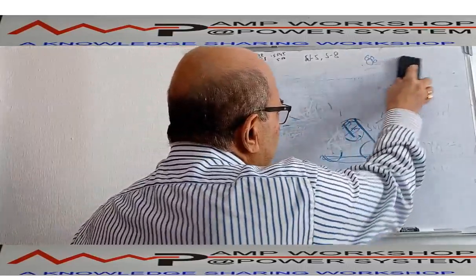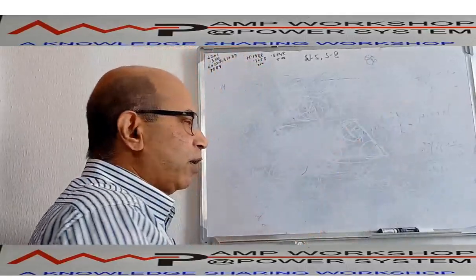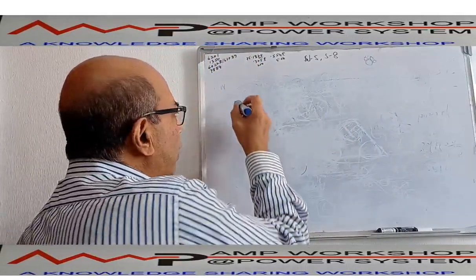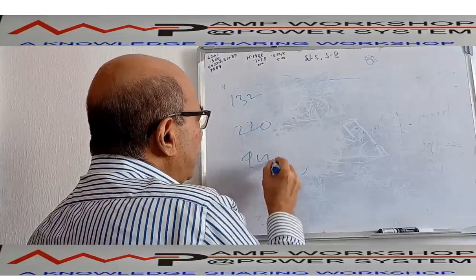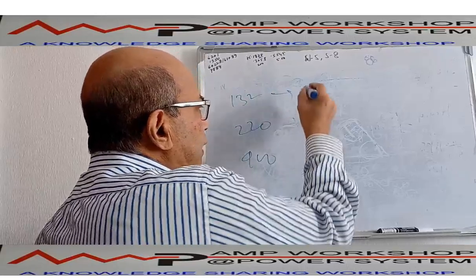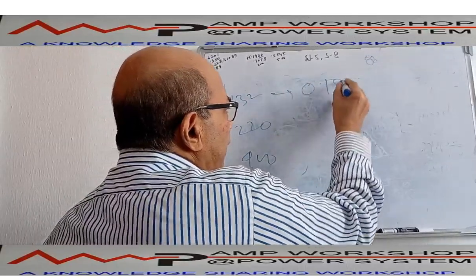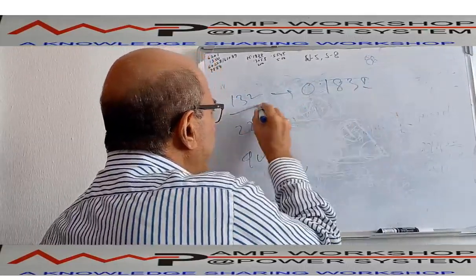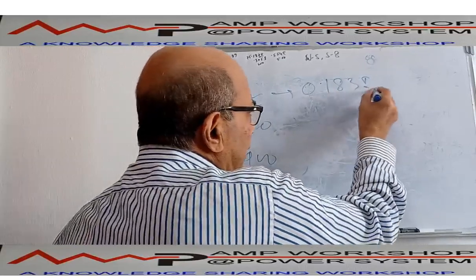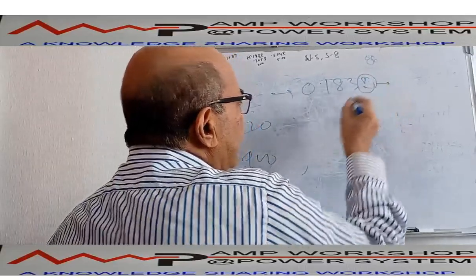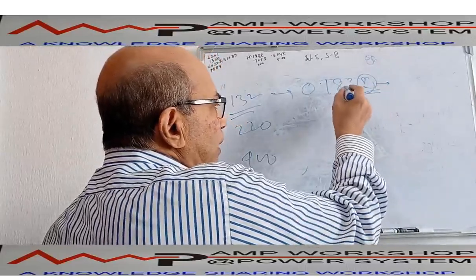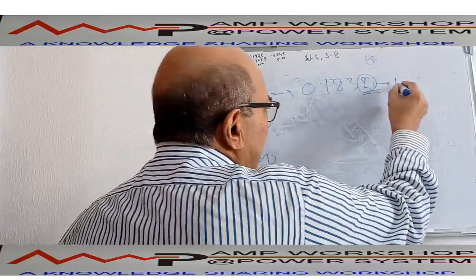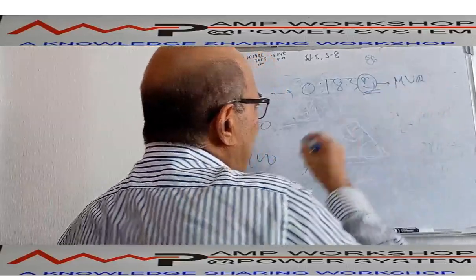overhead conductor details, how the conductor is designed, and what the brand names are. And for 3 voltage levels, I am writing one formula, for 132 kV, 220 kV and 400 kV. If you see the power carrying capacity, it depends on the current. Voltage is 132 kV. If I is the full load current in ampere, suppose 100 ampere current is going, how much power will it carry? 18.3 MVA. This is the capacity in MVA, the current power carrying capacity.